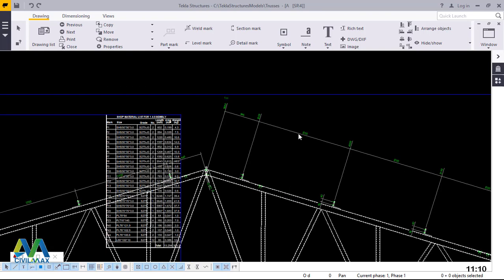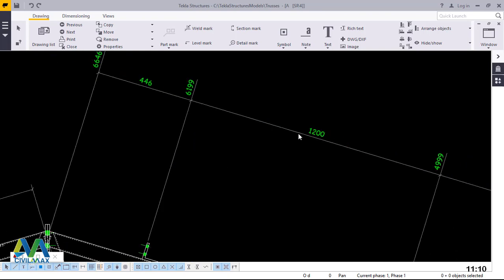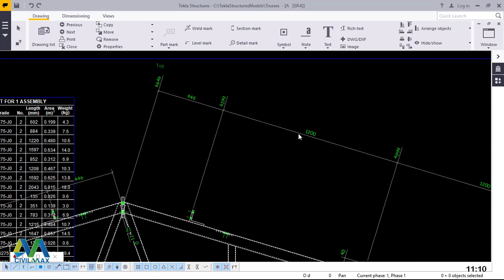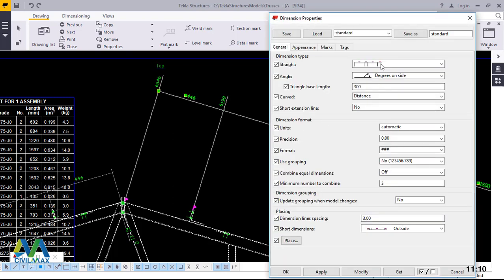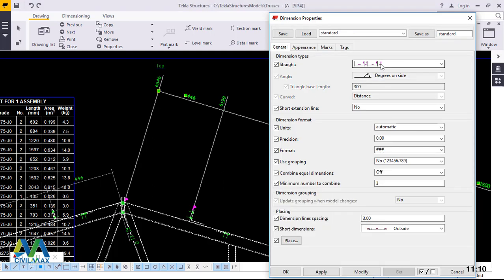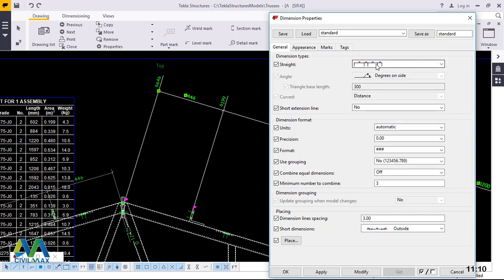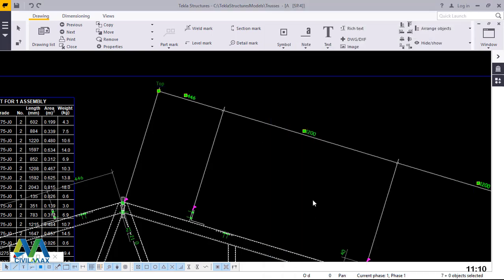And I'll change this cumulative to the conventional way of doing the dimensions, because some people will really struggle to interpret the cumulative dimensions. They'll keep on asking you, what is this, what is this? So you'll get tired explaining a single thing several times. Now we better change to what people understand much better, which is the conventional dimension, the normal one. Click modify and apply that, then give a nod by clicking an OK button. I'll apply, then click OK.